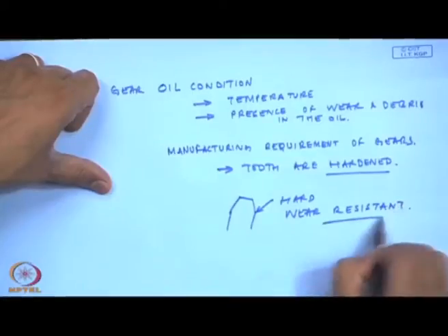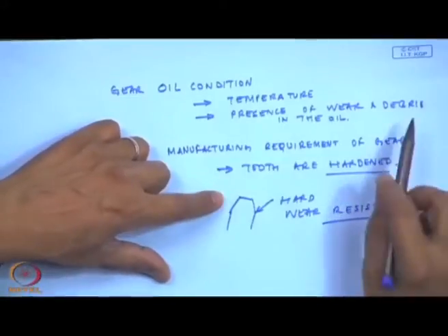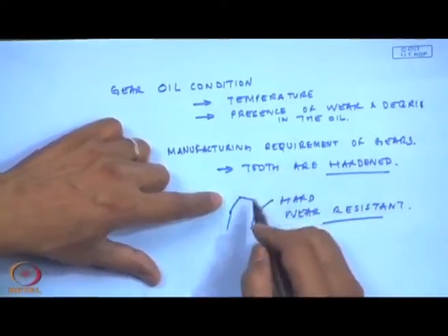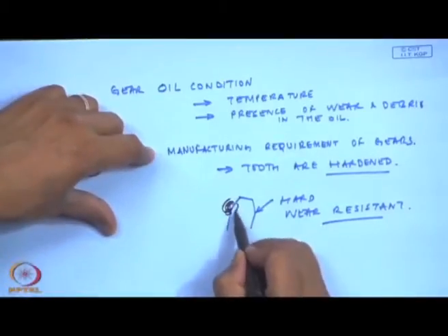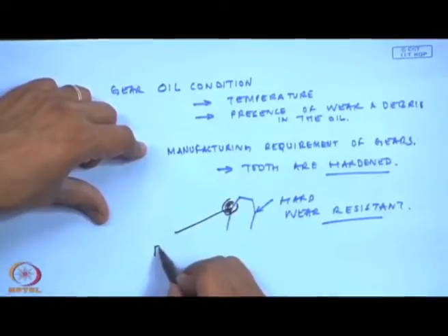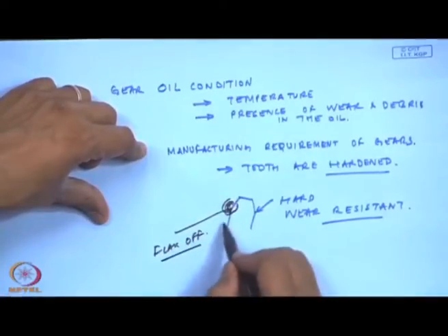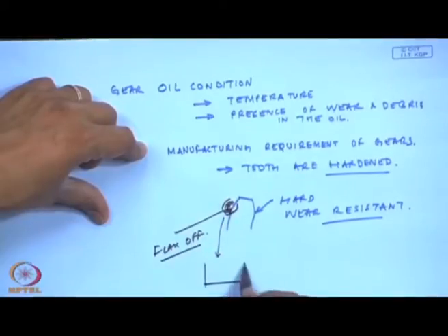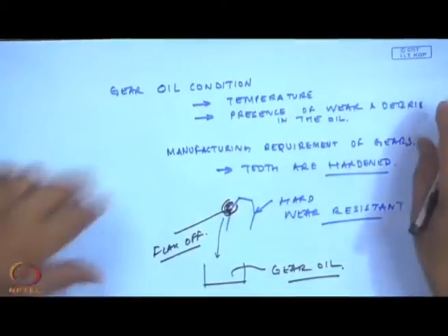So, many times what I have seen, if a proper heat treatment is not done on the gear tooth, these particles will flake off. And these particles will get deposited in the gear oil. So, to find out the defects in gearboxes, many techniques can be used, and which will come one by one.